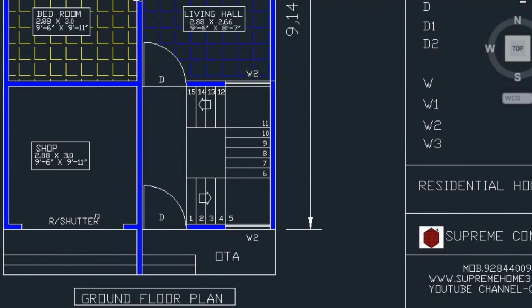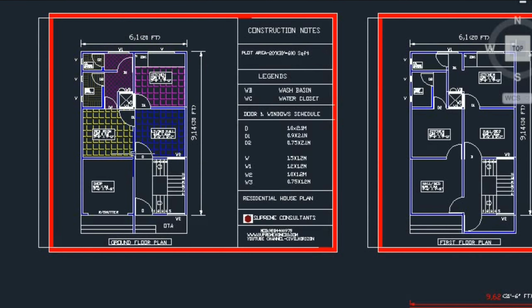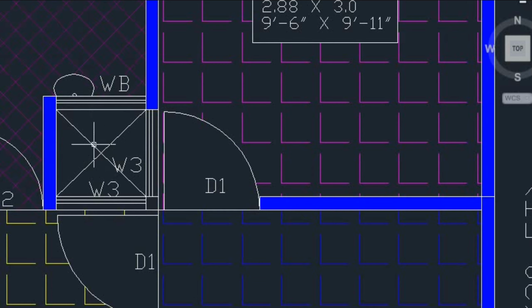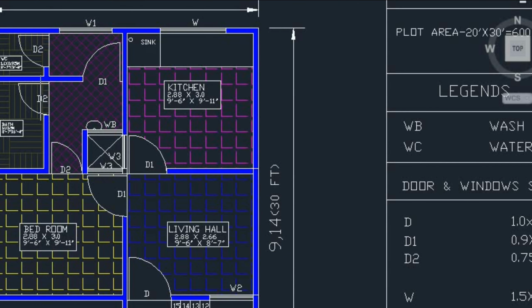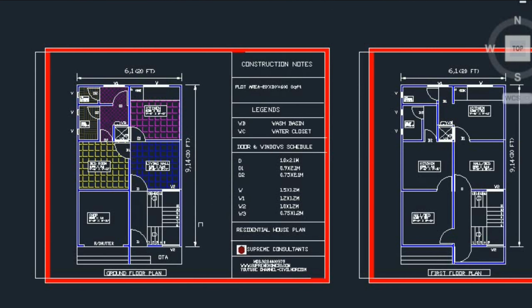Architectural design features. So I have planned the entire building floor wise, and what I have considered is all the rooms are as per the client requirements. Stair is planned in the front portion because it gives elegant look and easy access to tenants without causing any disturbance to others. Duct is provided for light and ventilation purposes near washrooms and kitchen.